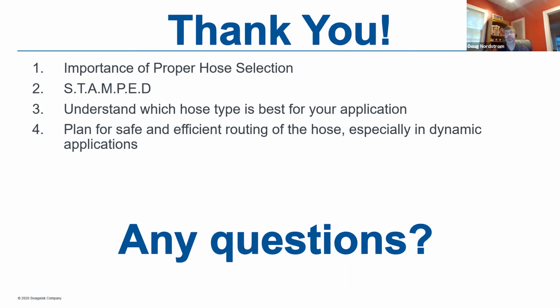We'll get into permeation a lot more in part 2, but we see an enormous range in performance just within PTFE, and it depends on how the actual core tube was made. You can have about 40 times difference from one manufacturing method to another. So it is important to understand how the hose is made when selecting a PTFE hose for gas applications.